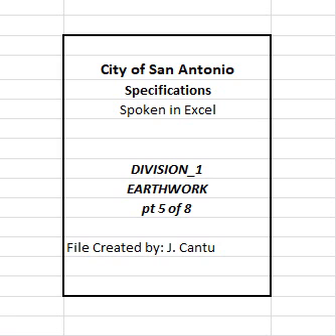Remove small areas of the layer to allow for density tests. Replace the removed material and recompact at no additional expense to the city. Proof roll in accordance with TxDOT Item 216, Proof Rolling, when shown on the plans or as directed. Correct soft spots as directed.